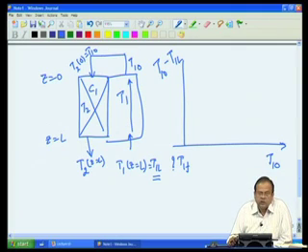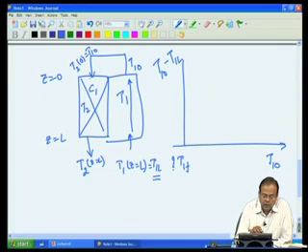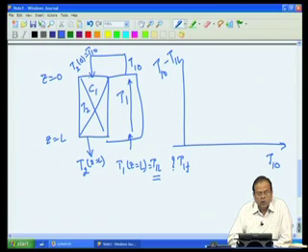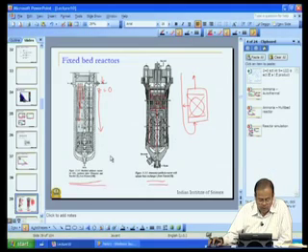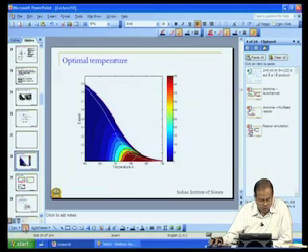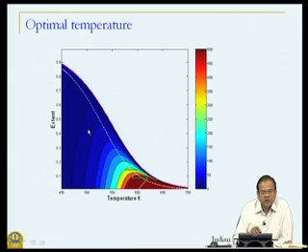Now, again, this is all a qualitative argument. Let us assume that my T10 is very low. We saw that if the temperatures are low, the reaction rates are also very low, right. If you do not recall, we will go back to temperature versus rate, and these are my rate contours, colors from low rate to very high rate.